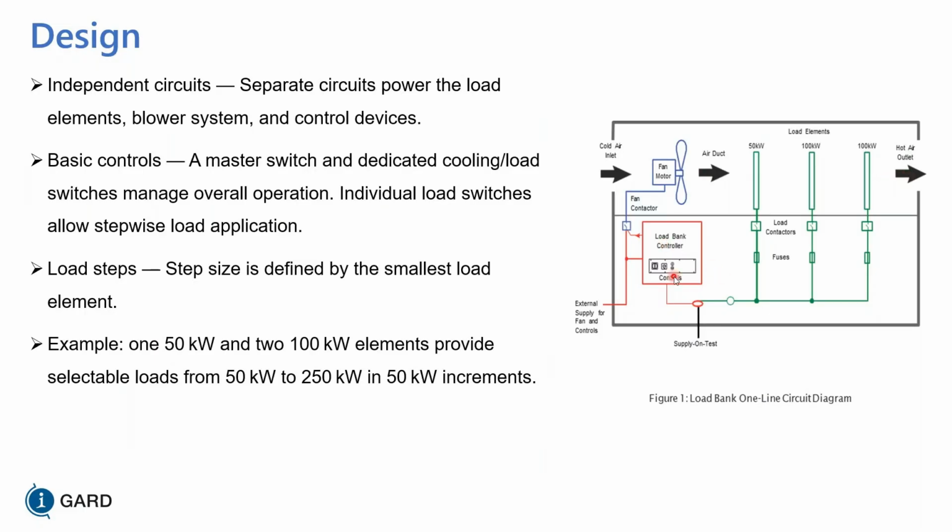So in the last session, they asked if your controller can be hooked up to a SCADA system. Yes, it can. All you have to do is we can provide the contacts here. You just tell me what voltage you're going to come in with to control the load banks, and I can provide those contacts to make sure that this thing is going to function through your SCADA system. And while you're doing this, you can measure the output temperature and measure the stress on your HVAC system if you wanted to go through that.